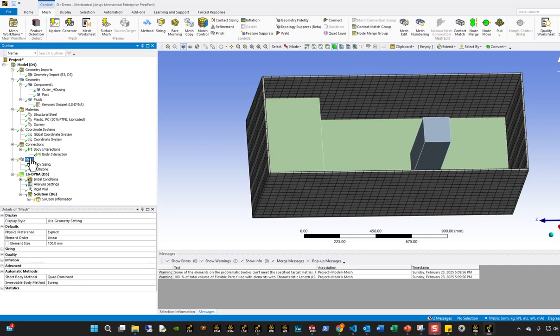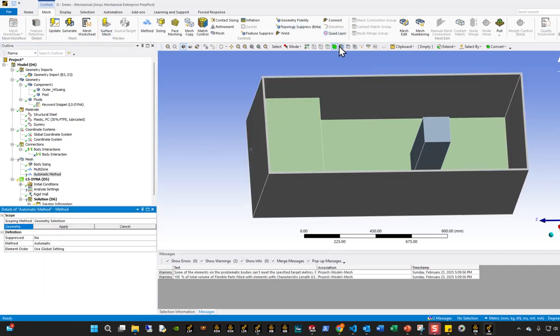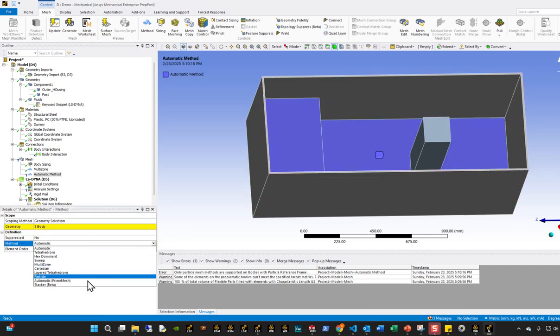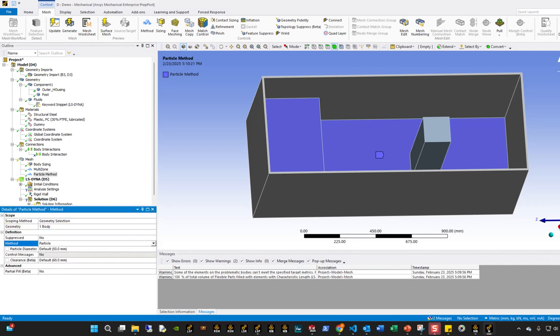We're going to add a method for the fluid, and I'm going to define this as a particle-based method, SPH. Right now, the SPH particle size matters a lot from the definition of the analysis. For this kind of problem, you really want the particle distance to be close together. From what I've been able to experiment and find out myself, I put a 7.5 in one problem, and a little bit closer in another problem.